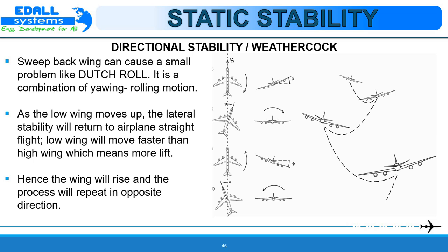Whenever the wing is disturbed from level trim, the aeroplane, left to its own devices, slips sideways in the direction of the low wing. Thus, the oscillatory rolling moment leads to some oscillatory sideslipping motion in Dutch rolling motion, although the sideslip velocity is generally small. The ratio of peak roll to peak yaw is usually less than 1 and is usually associated with the stable Dutch roll mode. However, when the ratio is greater than 1, an unstable Dutch roll mode is more likely.